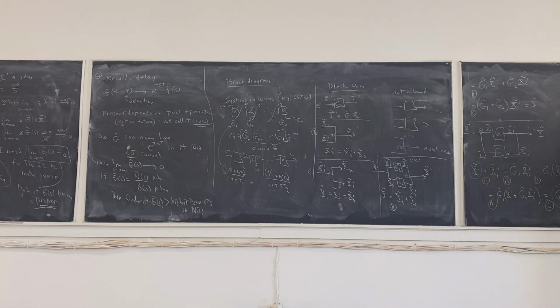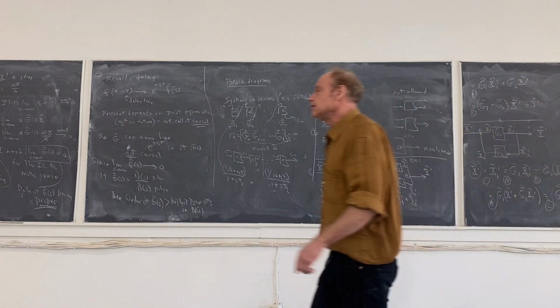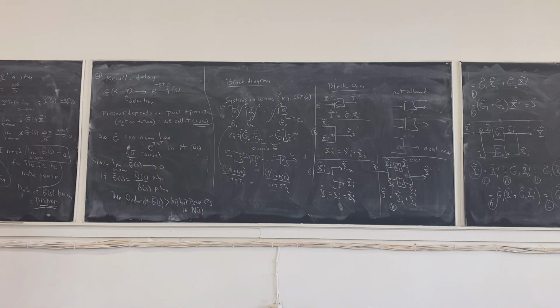And now you have a new denominator, and what you find is these denominators are much less stable in heat integration. So you have to be very careful how you do it, because as they say, when a butterfly flaps its wings in Beijing, it changes the weather here in New York. Because everything is so integrated that a little disturbance, you can see why. If there's a disturbance in this part of the plant so that the stream is not as hot as it usually is, then the input stream that's being heated up by it into this reactor won't be hot enough either.